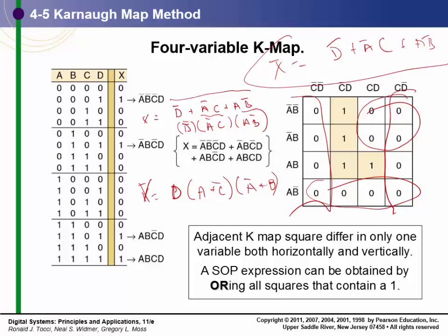So you're looking at this example, I read out the zeros and then I apply De Morgan's rule on it right here. I applied De Morgan's rule on it twice to get this right here, and then this is one application, and then this is the second application, and that gives me what the function is right there. So these slides show you very well how to handle the sum of products. They don't necessarily show you how to handle the product of sums, but what I showed you earlier on reading out the zeros gets us to the same place right there.